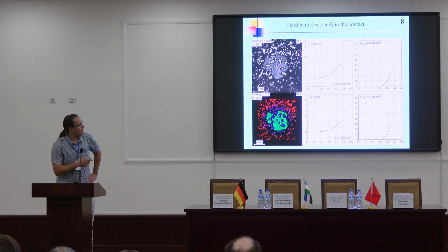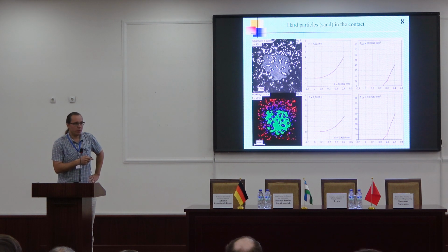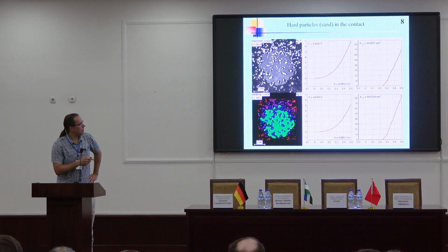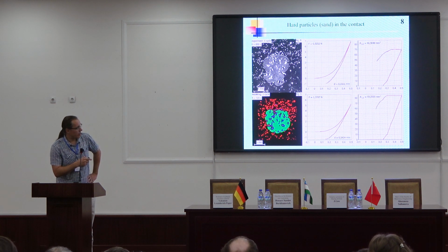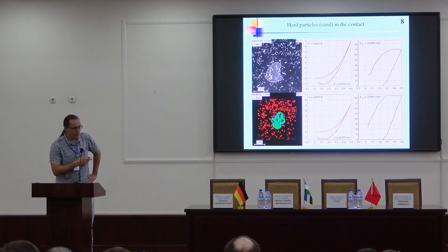Firstly, we have an increase of normal force without direct contact between rubber and indenter. And after some time, there is direct contact. It can be very important for applications such as rubber seals, for example. And it also can be simulated. We have got very good coincidence between experiments and simulation, I think, including the form of the curves.